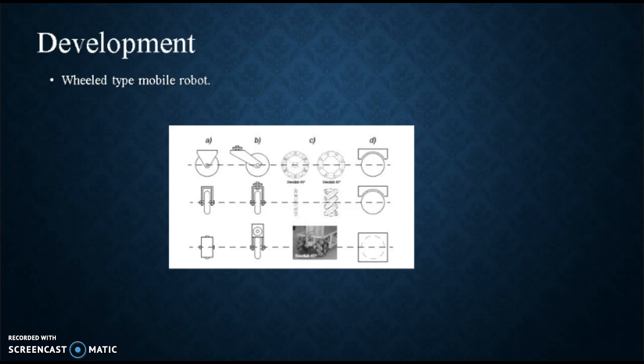The minimum number of wheels required for wheel mobile robots is 2. If the center of mass is below the wheel axis, static stability can be achieved by a 2-wheel differential drive robot. There is a very large space of possible wheel configurations. When one considers possible techniques for mobile robot locomotion, there are 4 major wheel classes for wheel mobile robots.